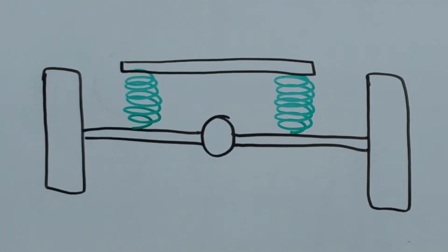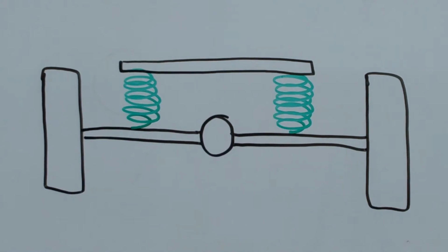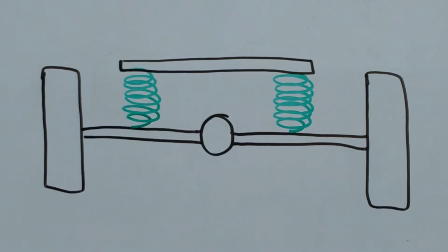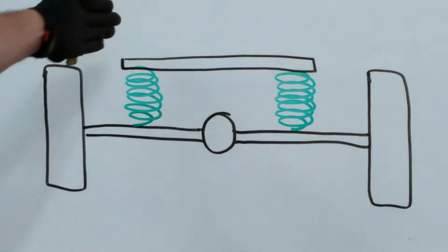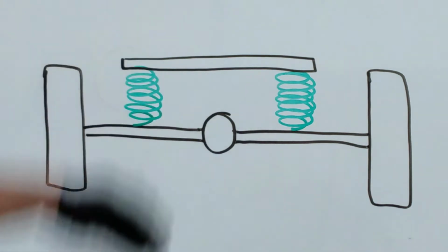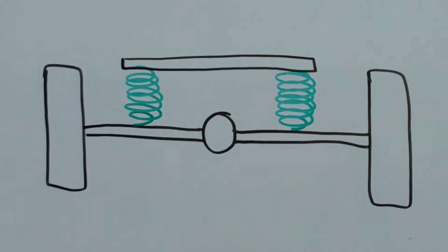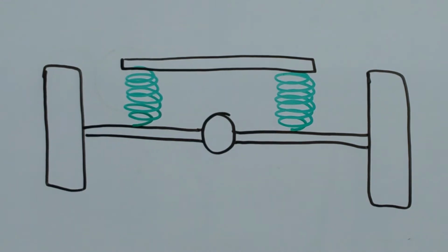So in this suspension example, we are using coil springs. Coil springs are inherently unstable. They require different control links in order to stabilize the components that they attach to, because they only offer stability in one direction, from end to end. That's the only way that a coil spring is supporting suspension. It does not control lateral movement or fore and aft movement. We need control links in place in order to use coil springs.